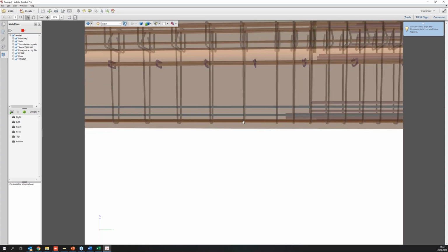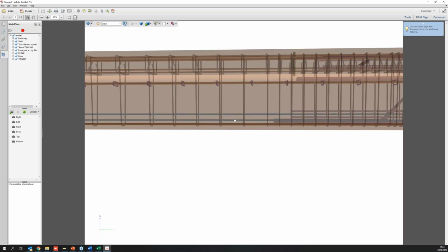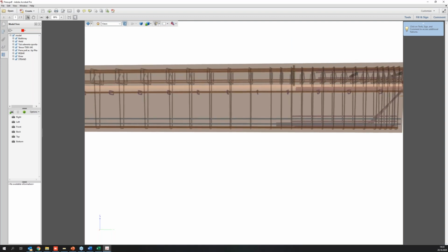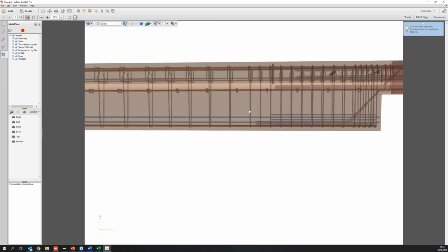At the bottom part of the purlin, we have some passive reinforcement. This is how we reinforce beams in Romania. I know that the current practice in some other countries might be a bit different, but I think the principles remain the same. So at the bottom of the purlins, we have passive reinforcement. Then we have pre-tensioned reinforcement, 2 layers of strands in this case.